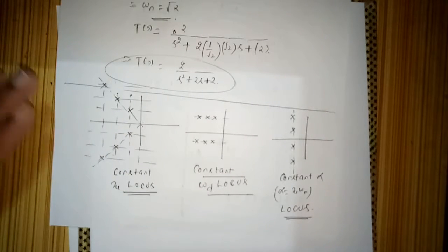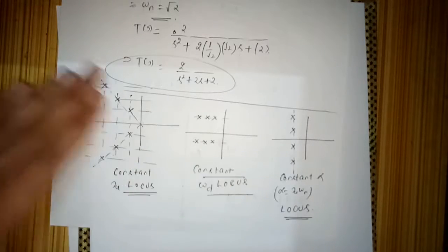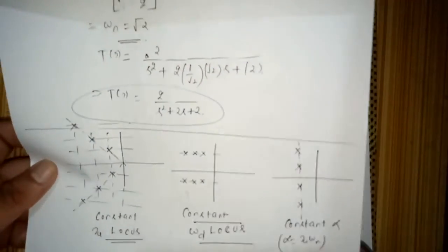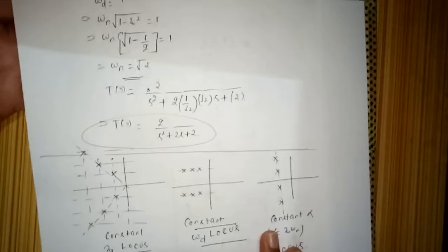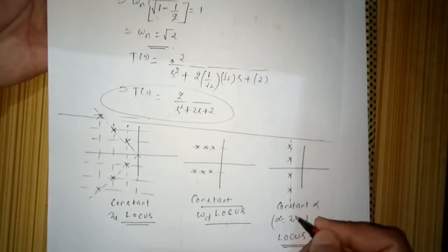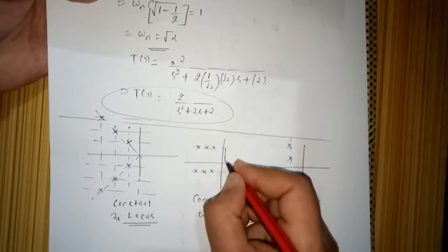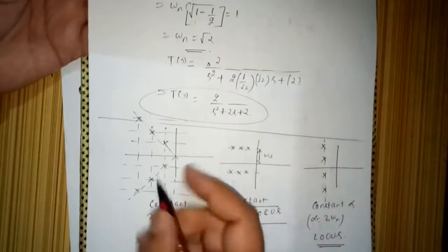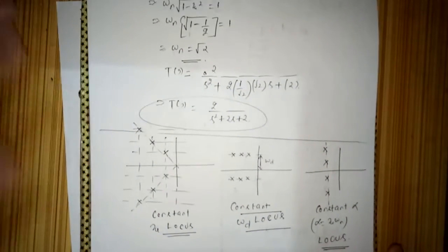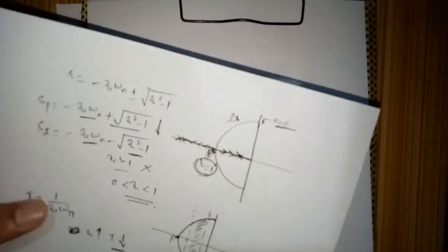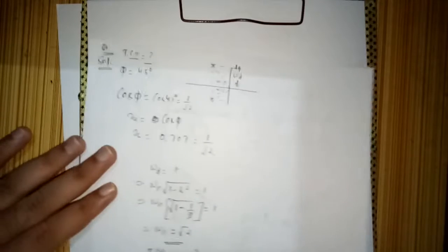These things are a little important. You should remember very quickly what is constant here, to solve questions with more speed in the exam. So you should be very comfortable. Have a look, spend some time on this, it is very simple: here it is constant zeta omega n, here it is constant omega d, and here zeta is constant, right? So that completes our discussion of damping, time constant and our pole zero location.